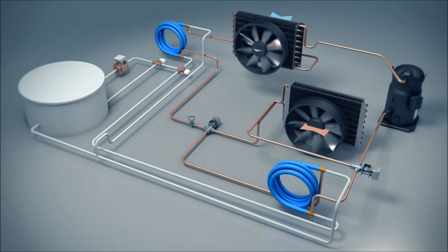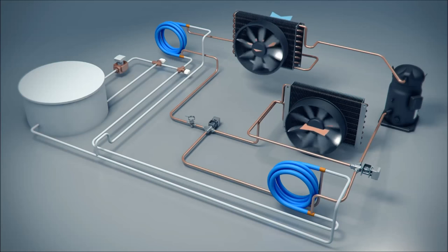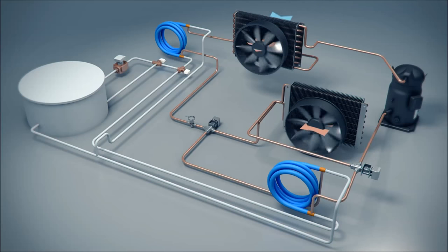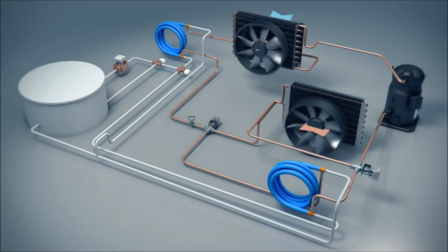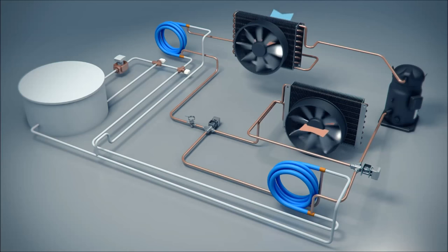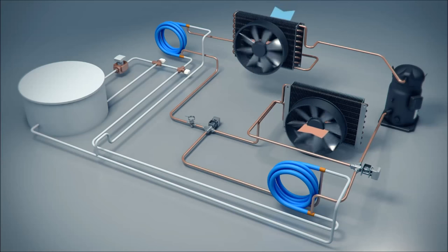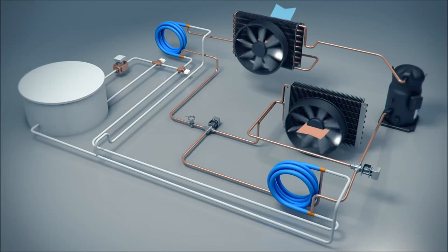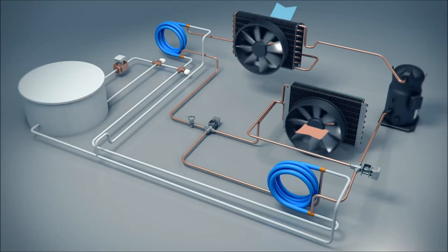The refrigeration loops are isolated from one another, operating independently through interconnected refrigerant valves controlled by the System Logic command module. Both heat exchangers, acting independently, are served by the hydronic loops sharing a common glycol pump and an ice storage vessel. These loops are activated through a set of three-way valves operating in conjunction with a controlled glycol volume at the heat exchangers and loop selection through the instrumentation and a time clock contained within the system control module.